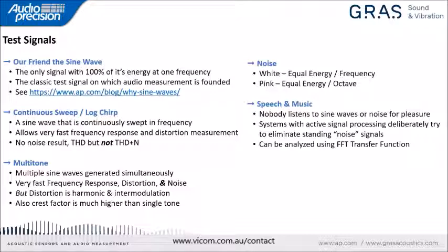Finally, because we have more than one tone, the crest factor is much higher. And one way of describing that is whereas in a single tone, all the energy in our waveform is at a single frequency, in a multi-tone, the energy is going to be divided into the different tones.